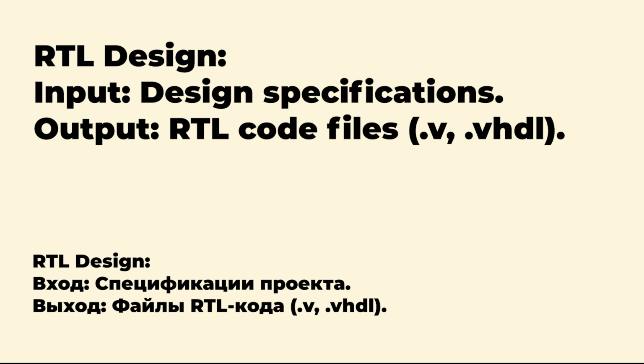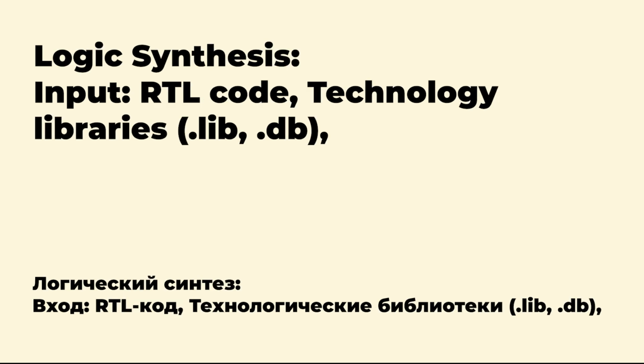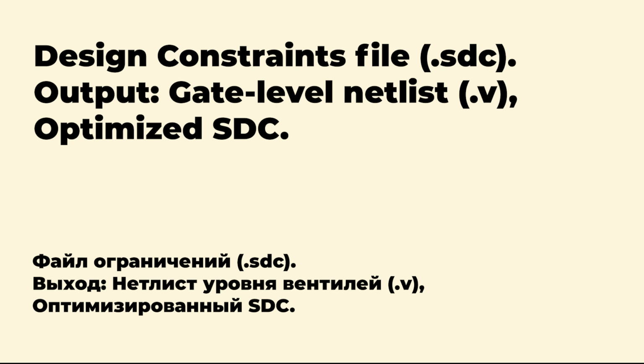RTL design. Input: design specifications. Output: RTL code files, .v, VHDL. Logic synthesis. Input: RTL code, technology libraries (.lib, .db), design constraints file, SDC. Output: gate-level netlist (.v), optimized SDC.